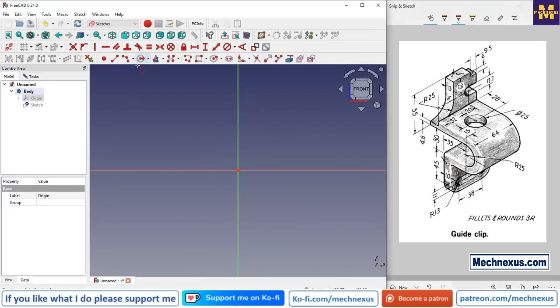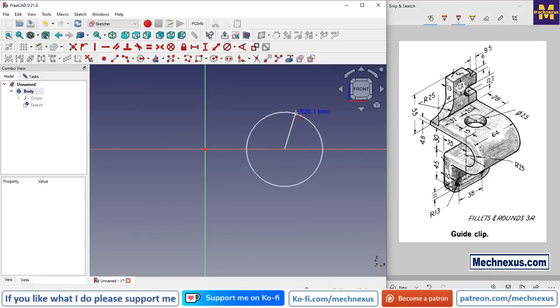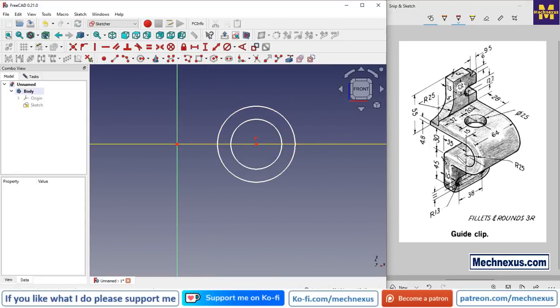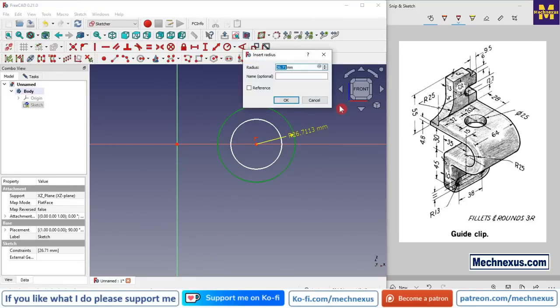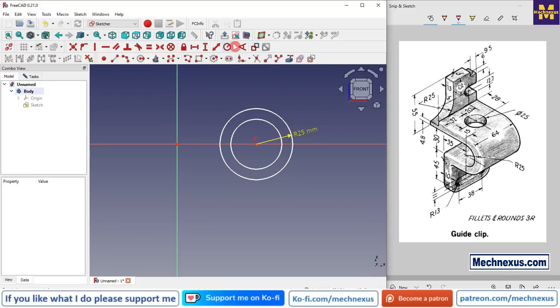So first I will create the two circles, and I will give a radial dimension of R25. So I will select it, select the radial dimension, and give it 25.